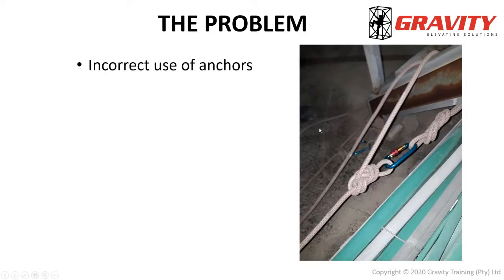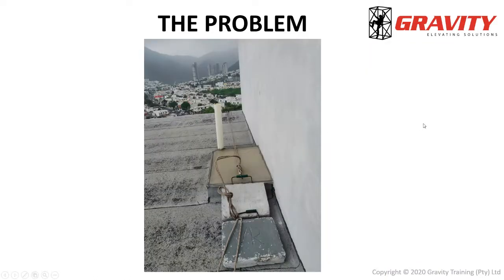So just a few more to give you an idea of what we're talking about. Again, guys using improvised solutions on site, using these deadweight anchors. As you can see, hopefully, none of these things are correctly fastened to the rooftop. They're not inspected. They're not certified. These knots are in terrible condition. Only one of them is taking any weight.